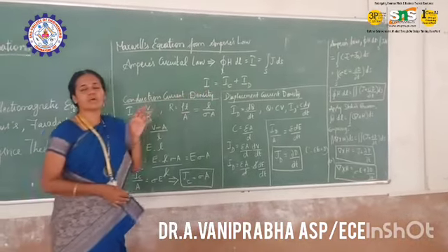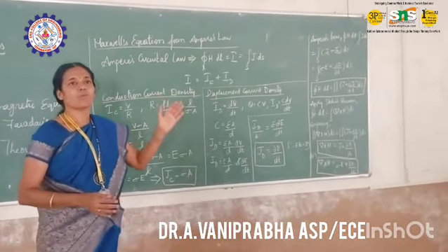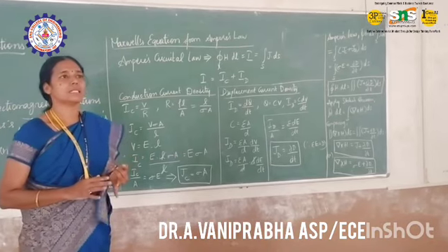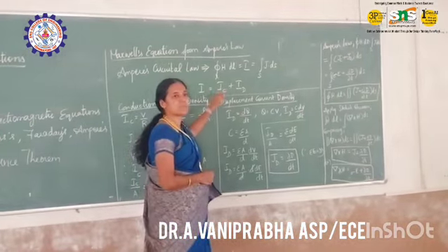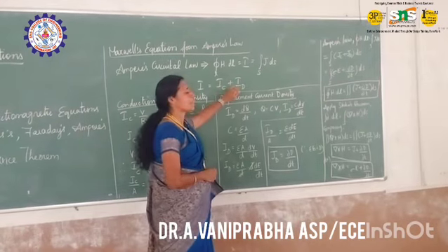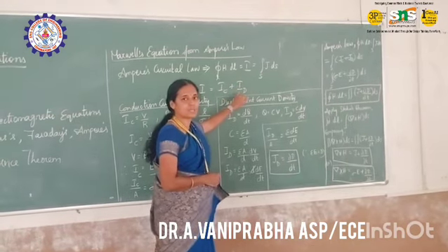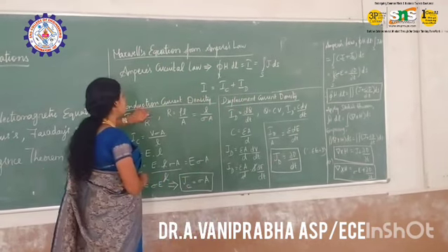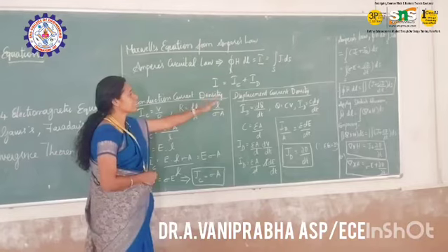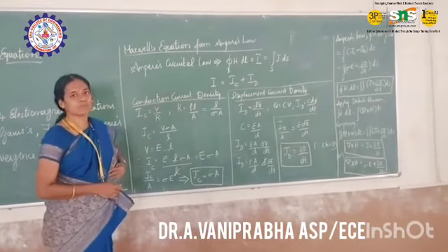We are talking about current. The current is a combination of both the conduction current and the displacement current. Current that flows through a resistive element is termed conduction current, and through a capacitive element is termed displacement current, which are IC and ID respectively. First, we have to derive the conduction current, and then we can go for the displacement current density.